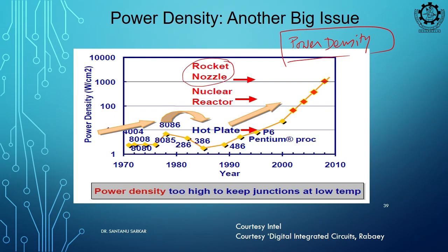So, the heat that is generated is sufficient to destroy your IC. What will happen? The metal interconnect may melt, creating a short or open. Your transistor could be destroyed, oxide could be broken. So many things can happen. Performance could be degraded, as we discussed last day, that the technological specification depends on temperature. So, they will vary, and your performance will vary.